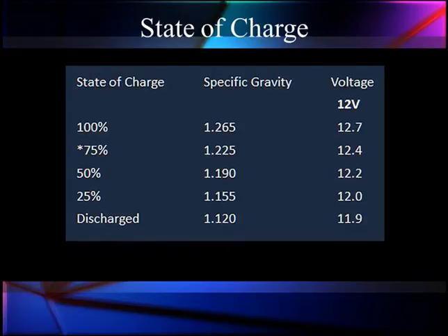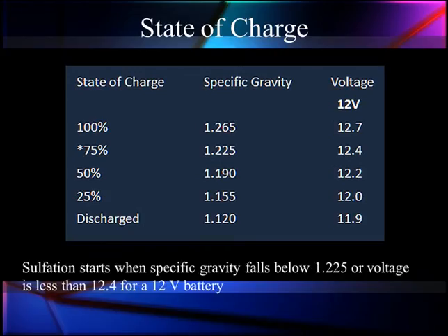One of my favorite questions to ask in class is, when is a 12-volt battery 12 volts? And the answer is when it's 75% discharged. What does this have to do with anything? Well, first of all, if we have a car that drives into a shop and we see only 12 volts at the battery, we know right away there's something wrong. But let's go in and explore this in more detail.